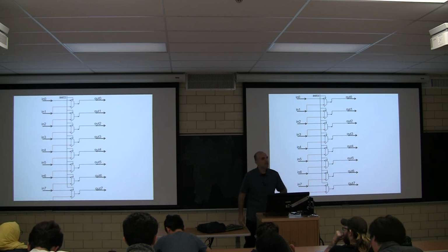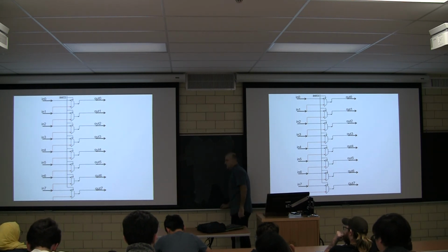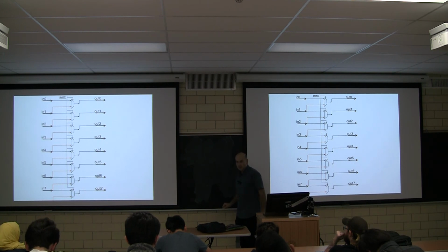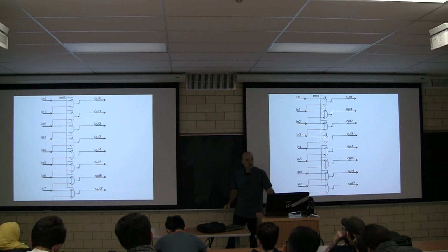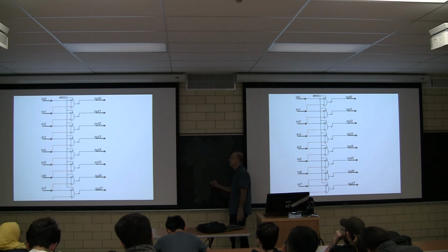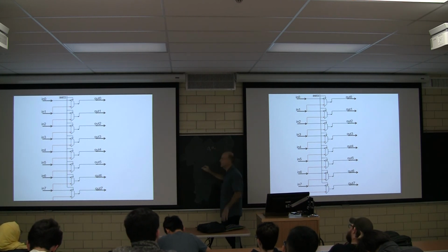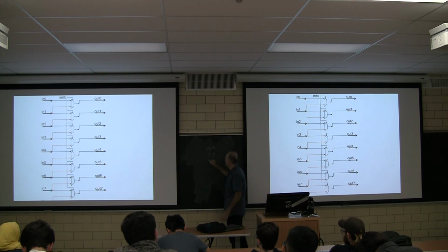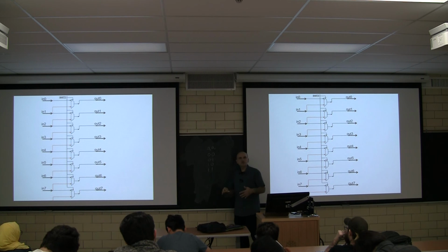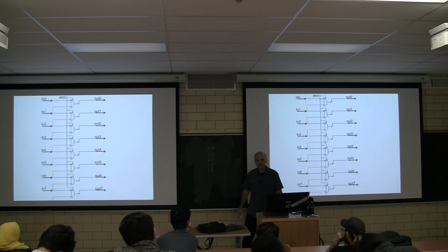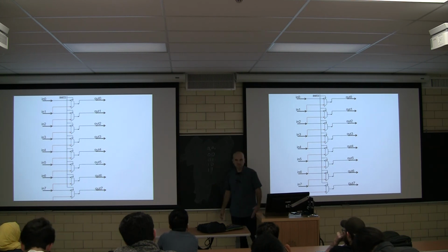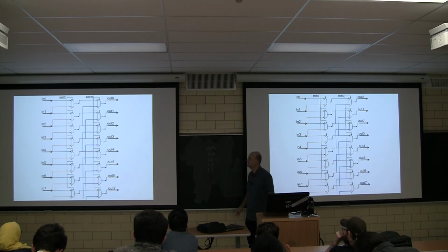Now, here's the thing. We just built a circuit that can shift by either 0 or 1 bit positions. How about a circuit that can shift by 0 up to 3 positions? You're going to give me a control signal that has 2 digits, A1 and A0. The possibilities are: don't shift, shift by 1, shift by 2, or shift by 3. I want you to view this as a 2-step process: this is either you shift by 1 or not, and this is you shift by 2 or not. Fair enough? This leads you to this structure.